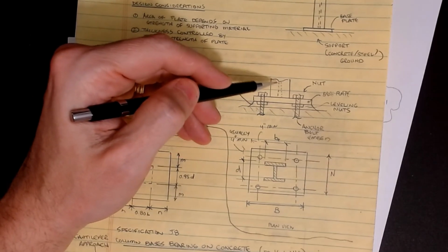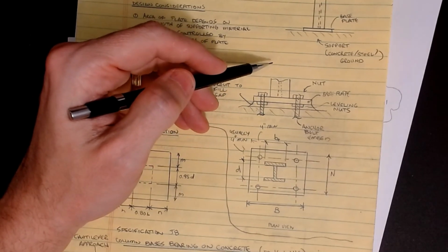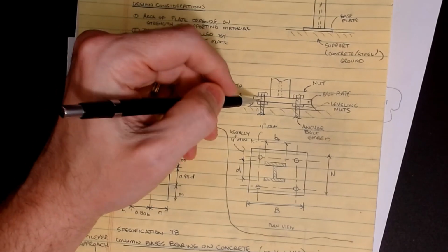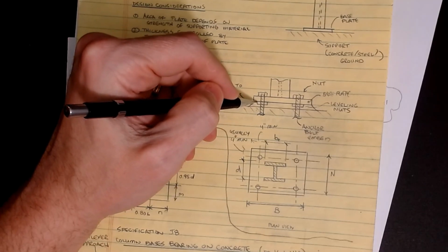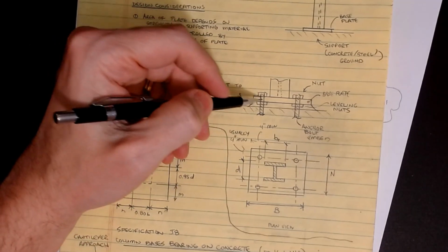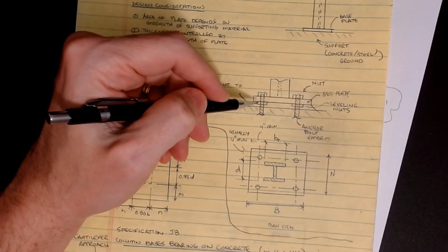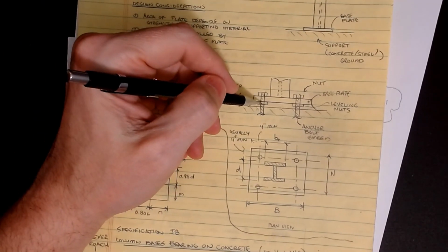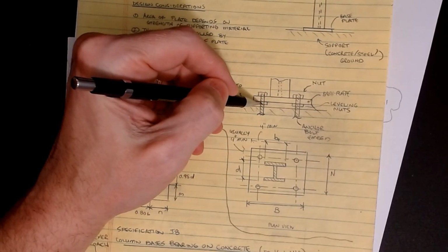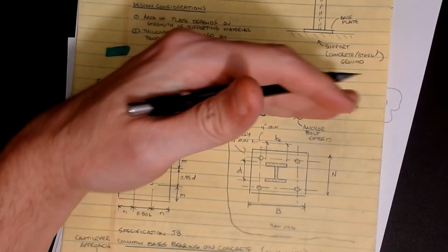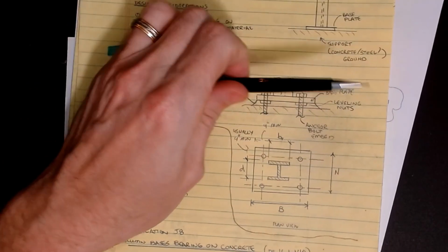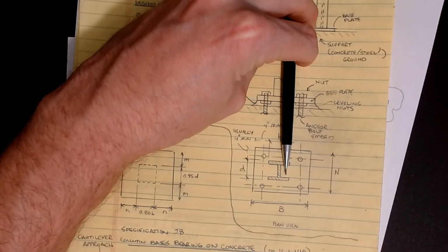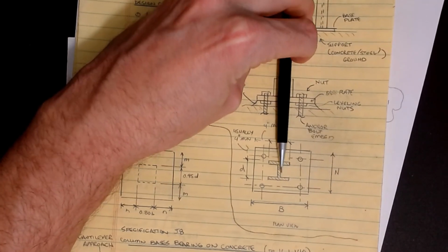It's the column that needs to be correct, because that's the one that has the holes and the assembly parts for the beams and the girders that are coming into it. So what they will do is they will put a secondary leveling nut on the rod underneath the plate and set it to a certain position, and then they'll set the column down on top of it. Okay, and then they'll adjust these nuts on the bottom side of the plate so that they can kind of tilt this thing and level it, so that if my column is leaning, I'm going to tilt it so that my column is now vertical. At the end of the day, that's all I'm worried about, is this thing being vertical.